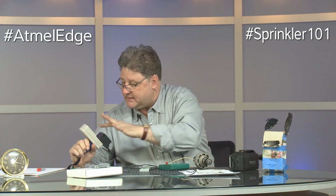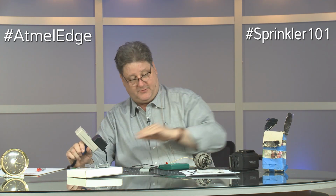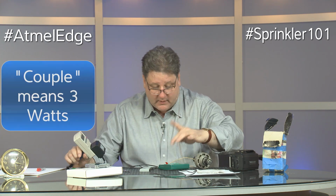Oops, I can see I accidentally kicked it out of watts. 5 watts. So it's taking 5 watts now. We know 2 go, 1 goes into the transformer, 1 goes into quiescent current in the product. Who knows what the battery is, probably minuscule, and then a couple of watts here. I don't want to burn this up, so we'll turn it off.